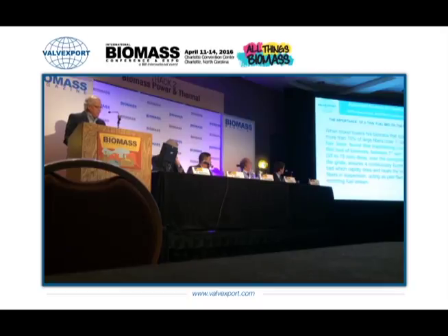Now, the importance of a thin bed on the grate is due to the fact that if you provide a controlled thickness of bed that burns between 1 and 3 inches deep over the complete area of the grate, this assures a continuously burning grate bed which rapidly dries and heats the biomass, fibers, and suspension.